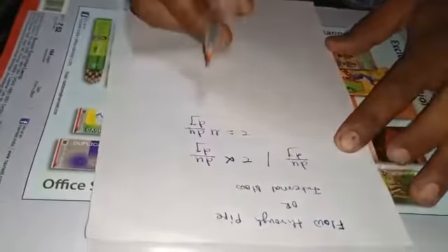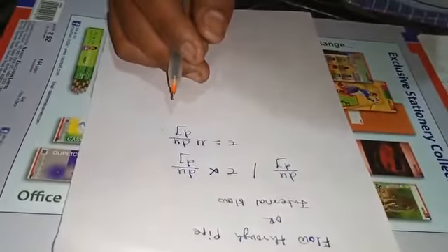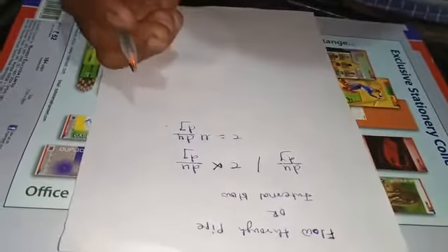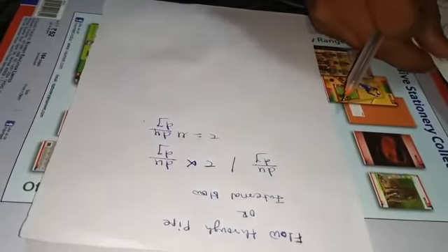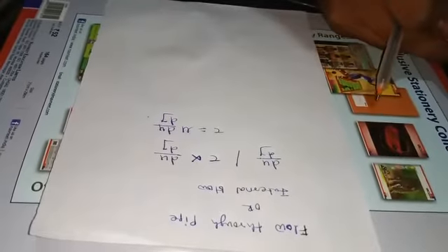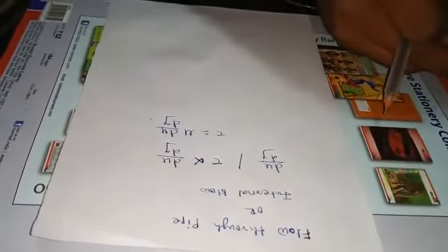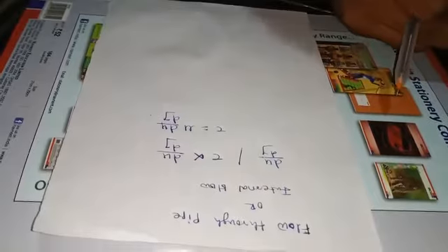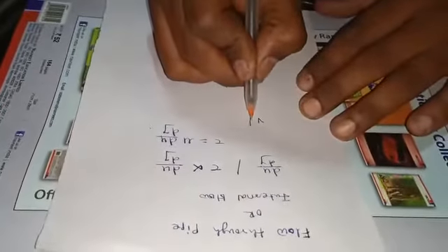As we know, in the second chapter we studied the various types of flows, in which we studied laminar flow and turbulent flow. In laminar flow, the fluid particles move along a straight parallel path in layers or laminae, such that the paths of individual fluid particles do not cross neighboring particles. But when the velocity is increased or the fluid is less viscous, the fluid particles do not move in a straight line. They move in a random manner. Then the resulting fluid motion is called turbulent flow.